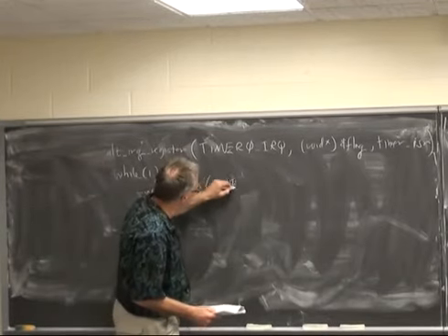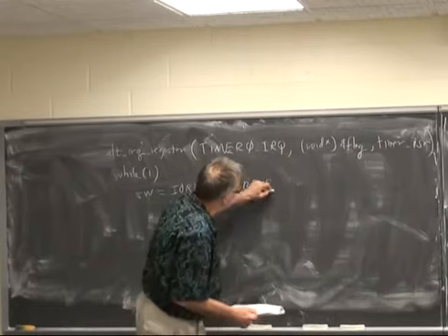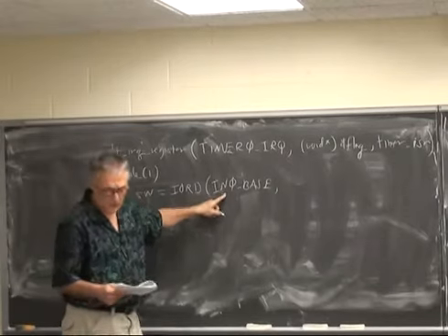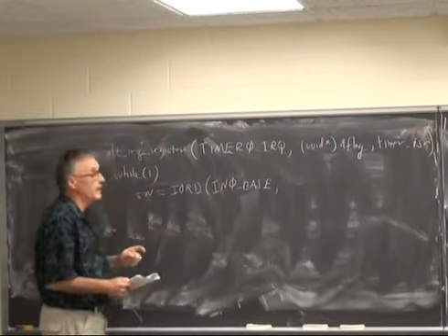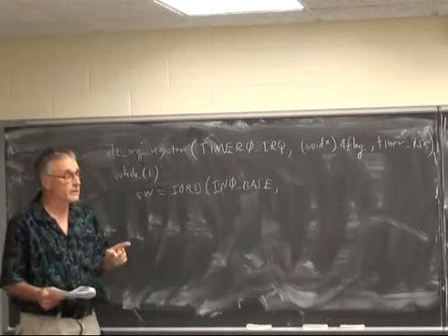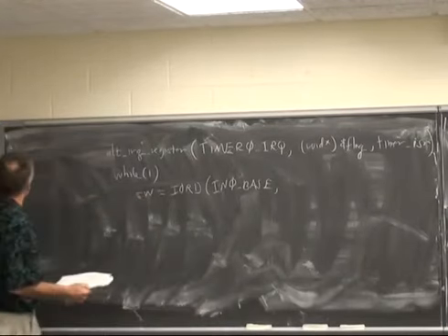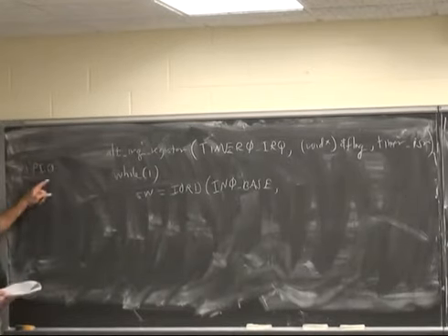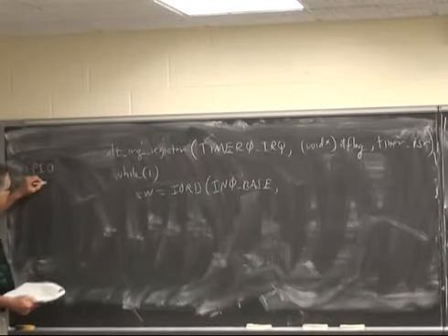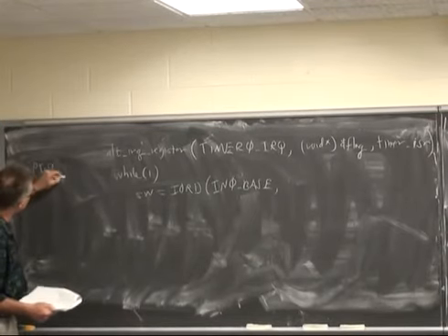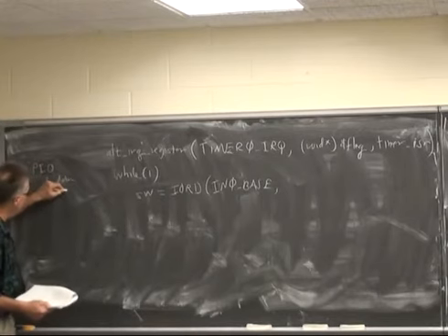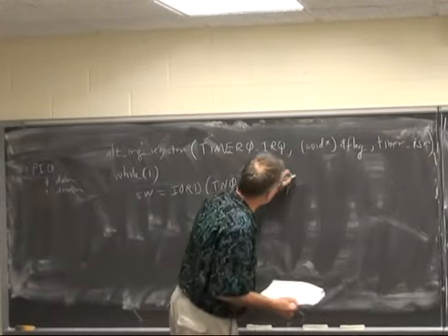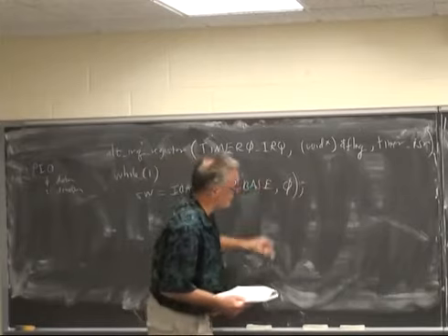Again, IN0_BASE is an address of the IO unit that comes from system.h, and it turns out that the PIO parallel IO control block has an offset 0 corresponding to data. Offset 1 I think is direction. So we want to read the data from this parallel IO device, so we're going to set the offset to 0.